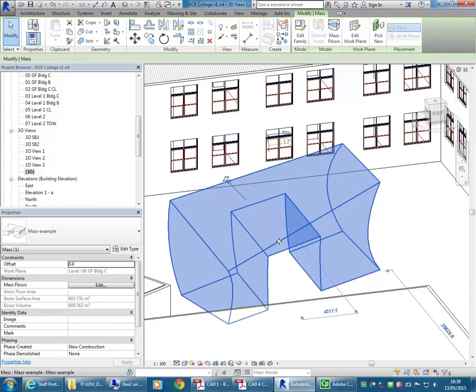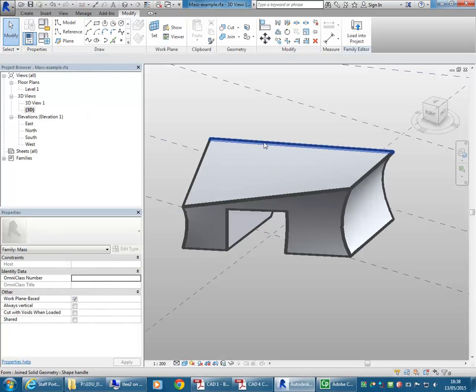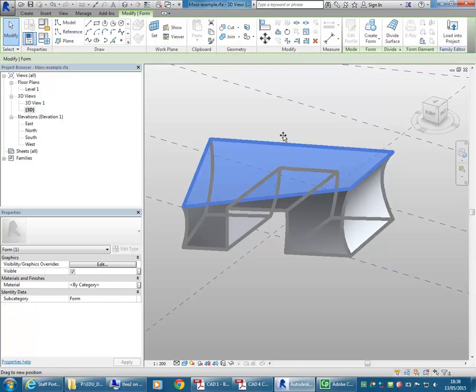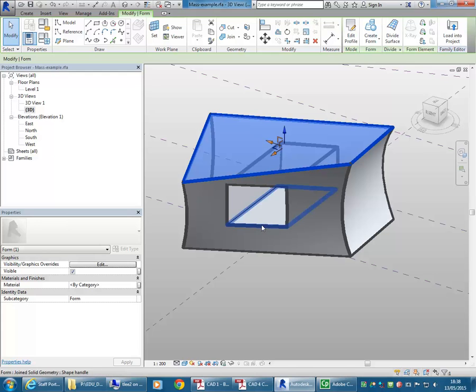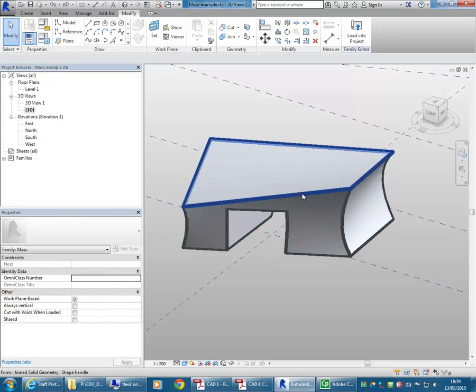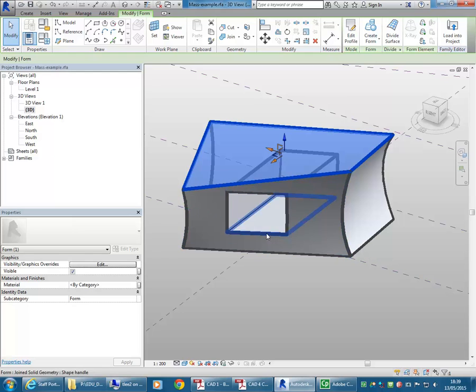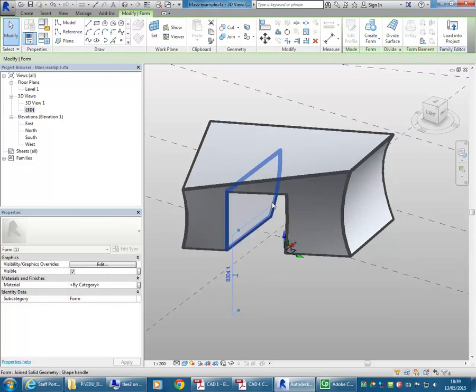or part of a building, and it's tall enough to be a building. So almost. I could make it have some stories if I just go back to the family once I select it, edit family. You've got to be aware of that toggle to make it visible again. So I'm just going to make this taller. Unfortunately, my void has gone with it, so I'll undo that and use Tab and make sure I'm getting the right surface there. And that's doing it again. That's okay. I'll just bring the void down.